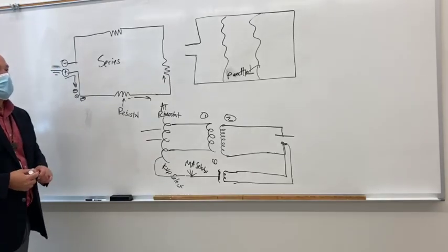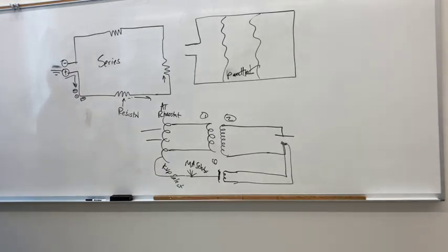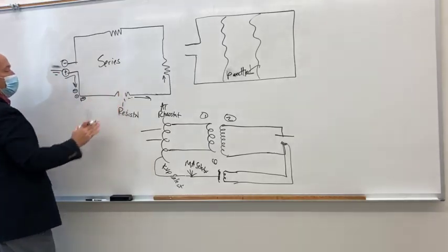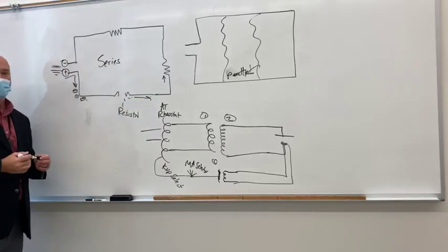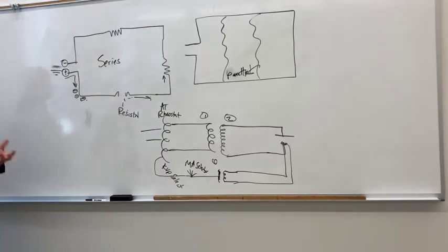All right, so let's say you plug in something in your kitchen. I got a problem in my kitchen. You plug into just the right plug, and all the plugs in the kitchen go dead. You seen something like that before? Okay, you blow this one here, then how is electricity going to get from here to there? It can't, right? So Christmas time, you got a string of lights, right? And one light bulb burns out, and the whole string of lights go out. That's what you're looking at.